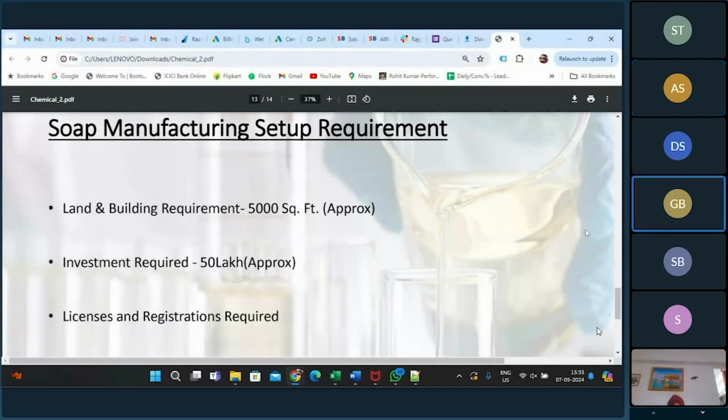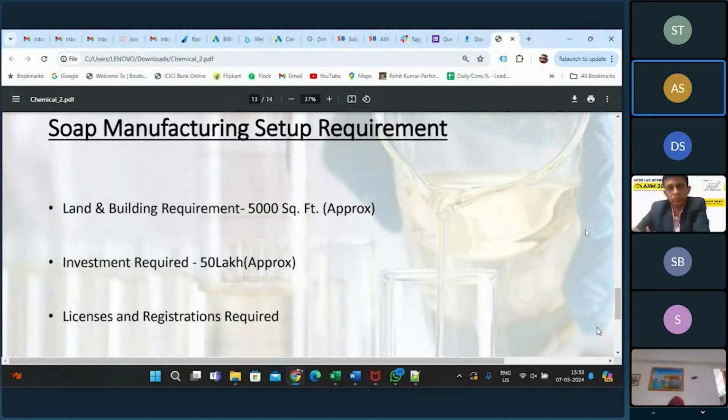Okay, and if I say that it is a batch process, for example, a mixing process of 100 kgs. So soap requires mixing and then extrusion. Okay, so it will have a batch mixing vessel and the extrusion part. If I consider a 100 kg setup, it will require approximately 1.5 to 2 hours to make it.